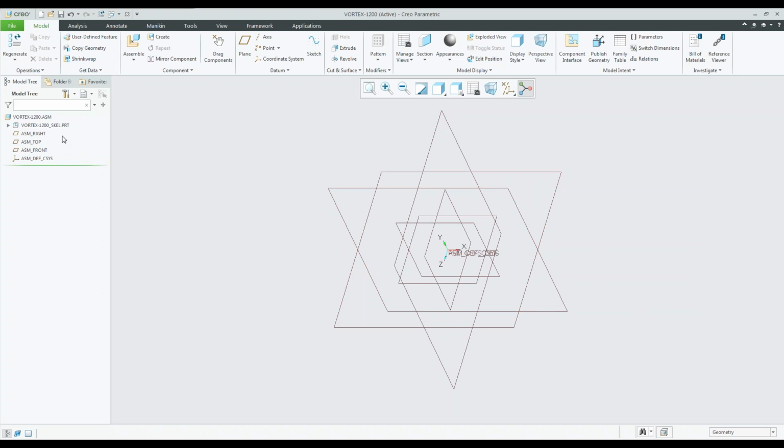Now, the skeleton, when you do add that in, it will be the very first component in the assembly at the very top, and that's where we want to make sure it stays during your design process. All right. Now, I do want to populate my model tree even further. I do want to add in the fan unit assembly, as well as the base unit itself. So I have two sub-assemblies that we're going to create. So once again, I'll start creating a sub-assembly, one for the fan unit. All right, let's say OK here.